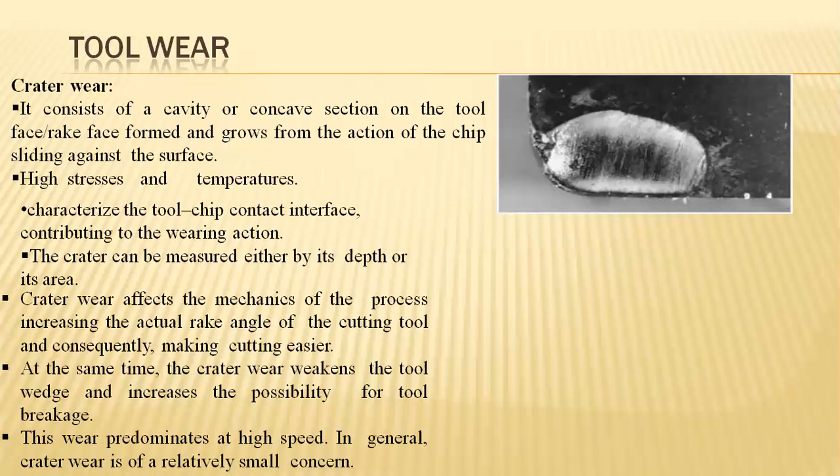Coming to the characterization of the tool, listen, at the chip contact interface, which is contributing towards the wear condition. See, nominally, where this particular edge is getting in contact for the machining process for the MRR condition, this tool should be in contact with respect to the work part. Nominally, it leads to the inducement of stresses, generating frictional forces which lead to a maximum range, and depending upon the coefficient of friction or frictional levels, high thermal stresses will be induced at the meeting point, leading to maximum deterioration.